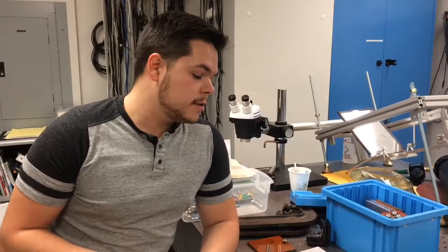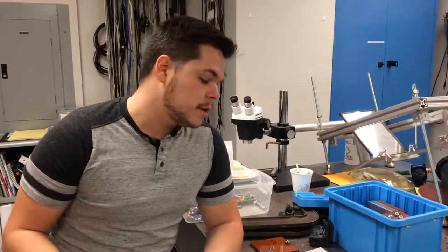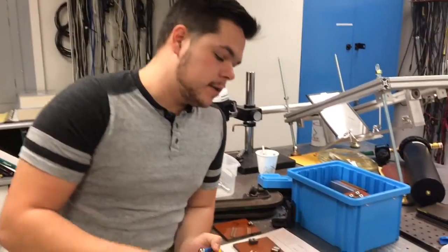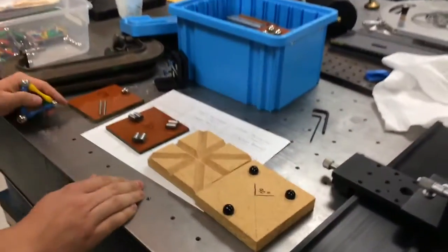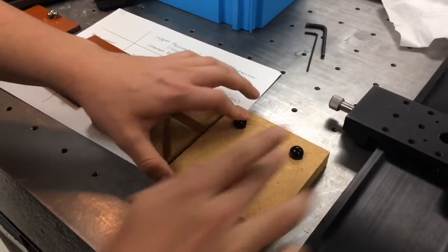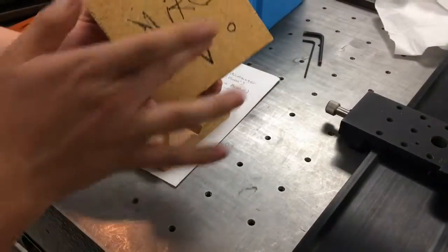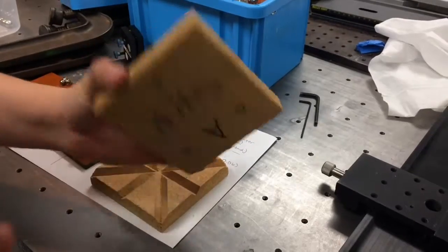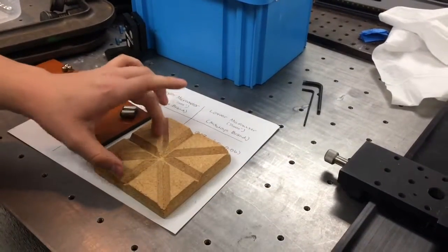So in practical optical systems, there are several different types of common kinematic constraints, but 2 of the most common ones, I'll start off with the first one, is the 3-ball and 3-groove orientation. This is one example. You can see that there are 3 balls. In an optical system, you can pretend there's an optic mounted to this surface on the back here, and there are 3 grooves.